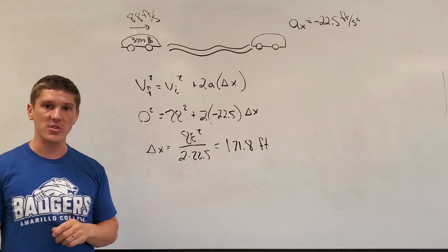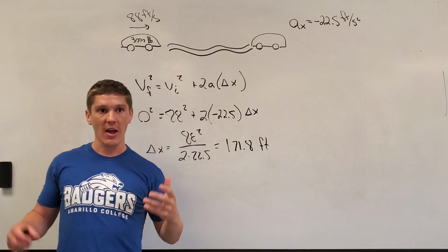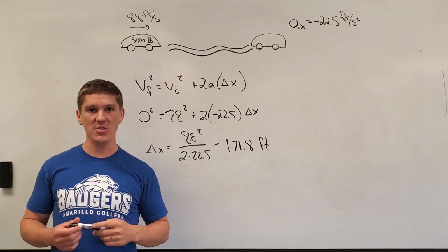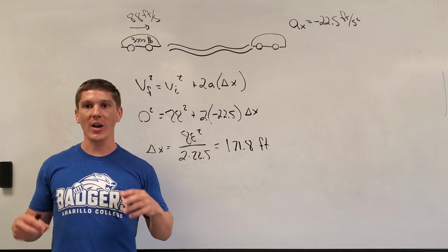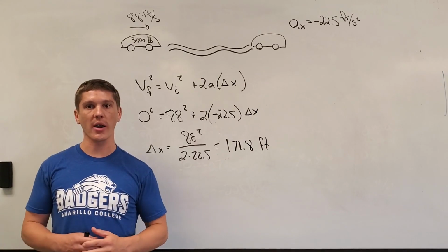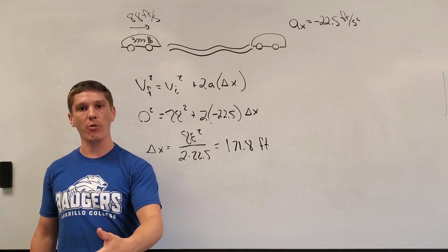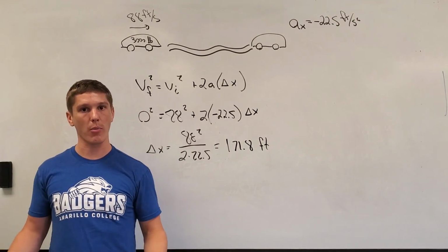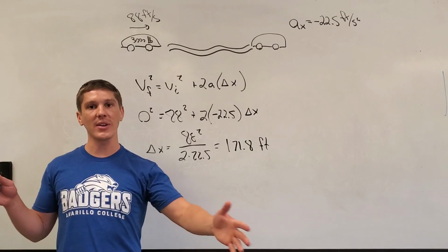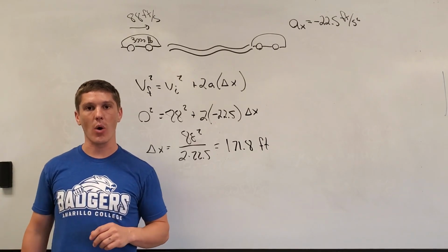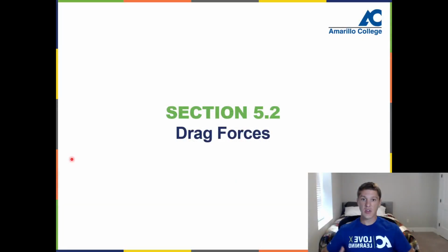So that's the importance of why anti-lock brakes have been adopted by all modern cars: those anti-lock brakes are what keep your wheels from locking up. And if you can keep your wheels from locking up, you get to use that coefficient of static friction between the rubber and the ground, and it can greatly decrease the distance it requires for you to brake to a stop.